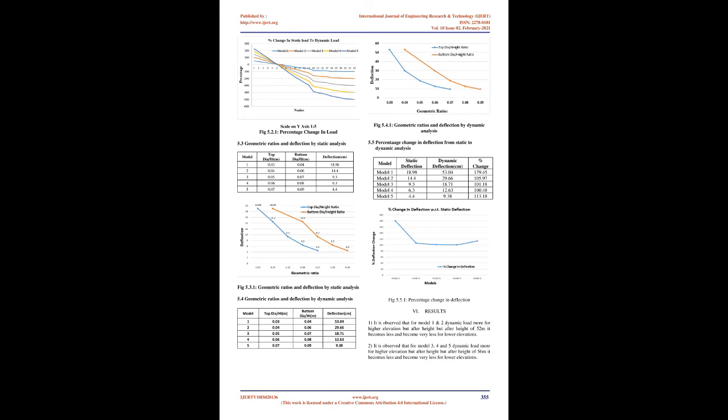The following are the details of the chimney considered. Unit weight of steel: 78.5 kN/m3. Height of chimney: 75 m. Maximum outer diameter at bottom: 6.5 m. Minimum outer diameter at top: 2.0 m. Thickness of shell at bottom: 24 mm. Thickness of shell at top: 20 mm.